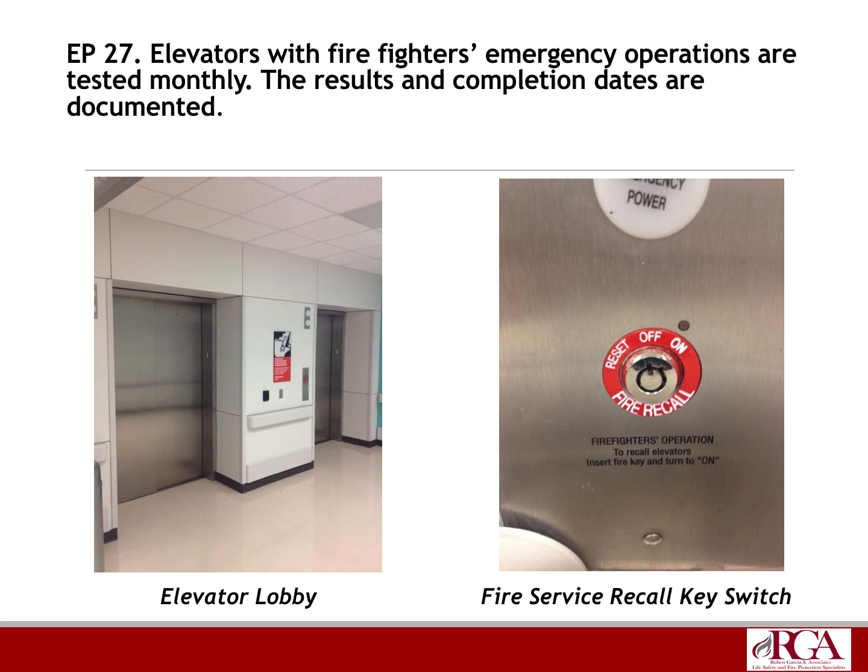So if there's fire detected in the shaft or the elevator machine room, which is the source of the elevator controls, that fireman's hat is going to light up. It's integrated into the fire alarm system. That relay will light that up, and it's going to let firefighters know, hey, this elevator cab is no longer safe to use. I need to exit as soon as possible, or else they can be susceptible to an entrapment in that elevator car. So that's just some bonus information there. But the phase 1, phase 2 has to be checked monthly.